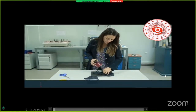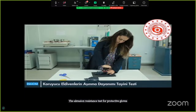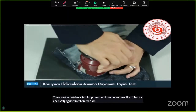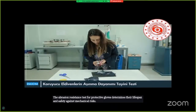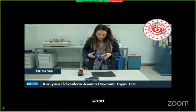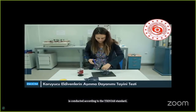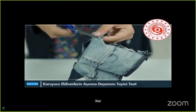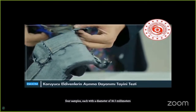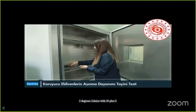The abrasion resistance test for protective gloves determines their lifespan and safety against mechanical risks. In our laboratory, the abrasion resistance test is conducted according to the TS-EN 388 standard. 4 samples, each with a diameter of 38.5 millimeters, are taken from the same production series and model of the glove and conditioned at least 5 hours.